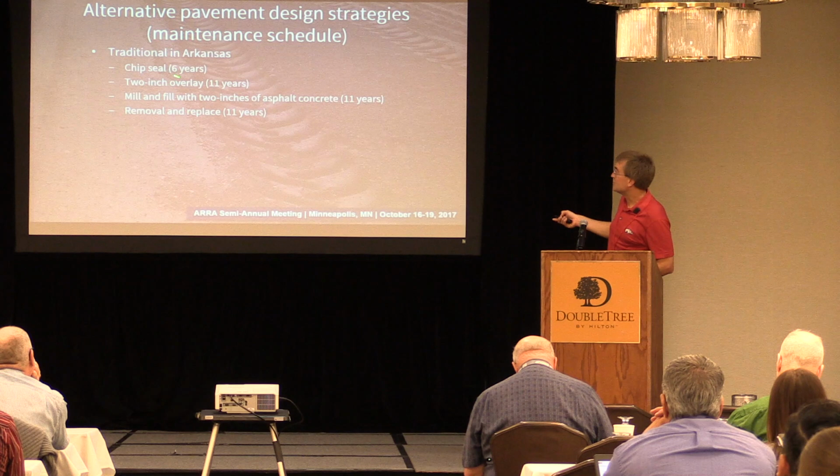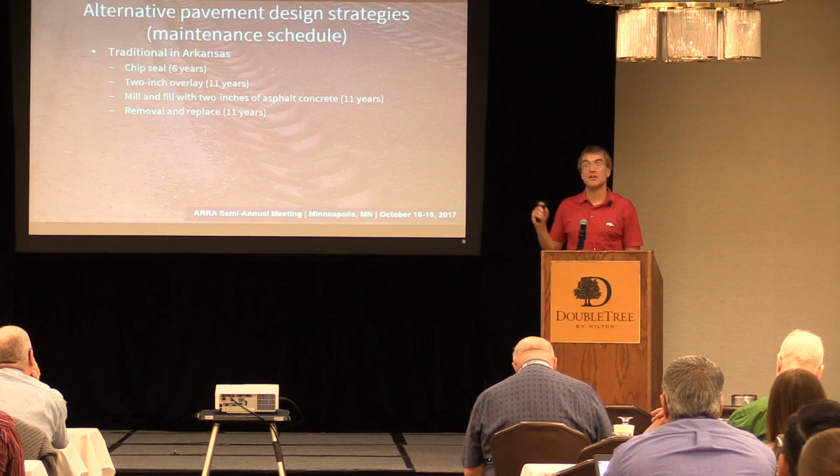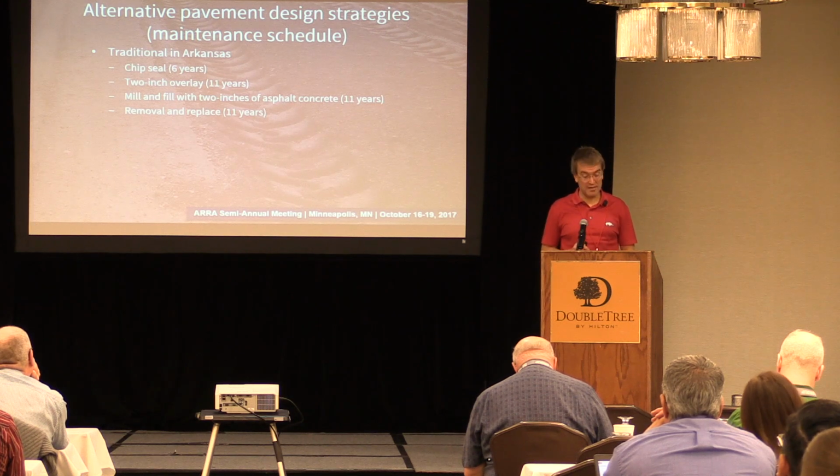The state of Arkansas generally does chip seals every 5 to 7 years, and they generally do a 2-inch overlay every 10 to 12 years. So that's how we got that 6 years and 11 years.